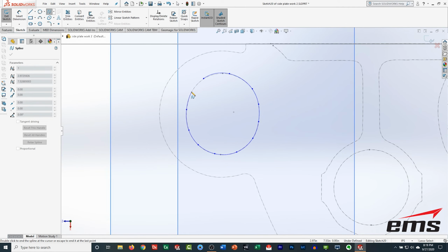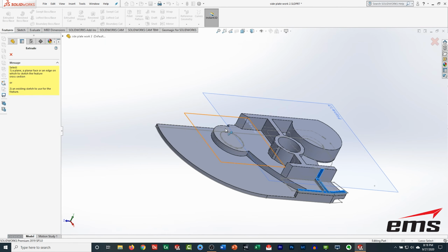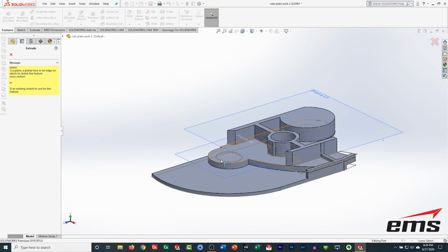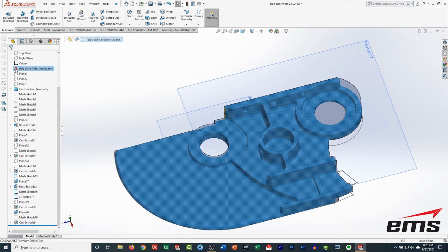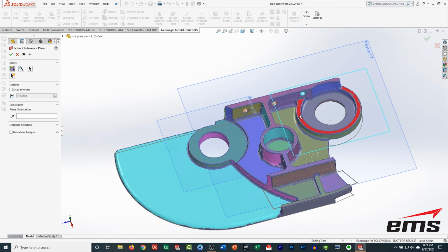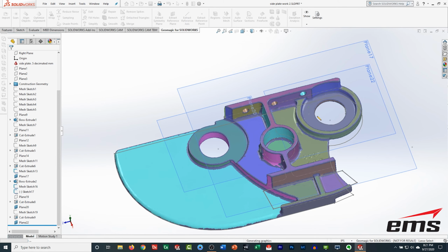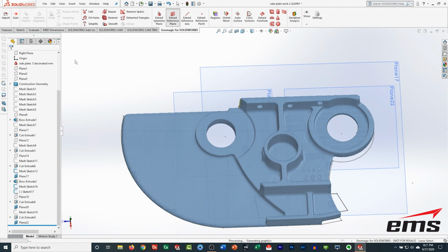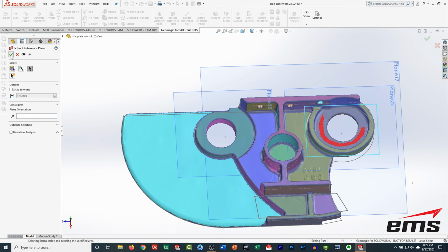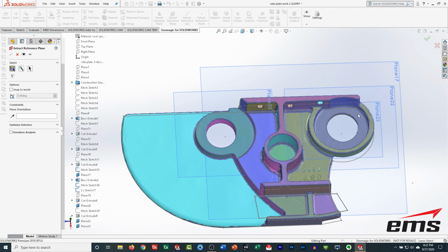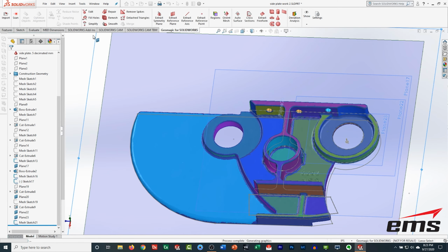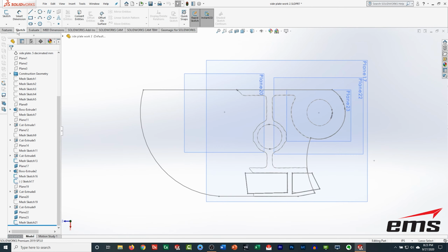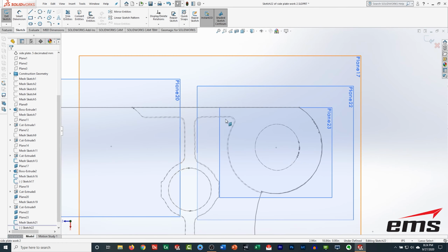Now this is not a circle. It may be like an oval, and you might be able to use an oval command. I just used the spline command and drew some points around for this, but however you want to do it. Again, it doesn't matter. If you give this part to two different engineers, they may both have two different methods of doing it, but at the end of the day, if it's correct, it doesn't really matter your method so much. Here we're going to cut out the hole in the bottom and then this slot itself.